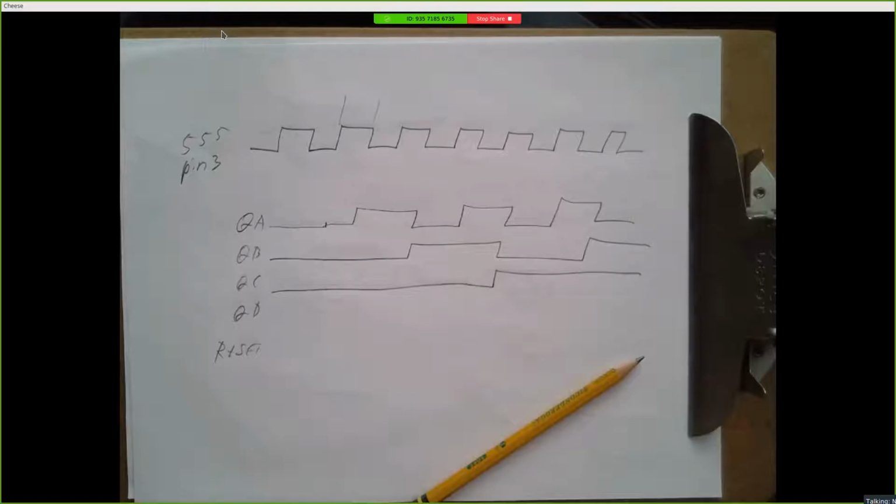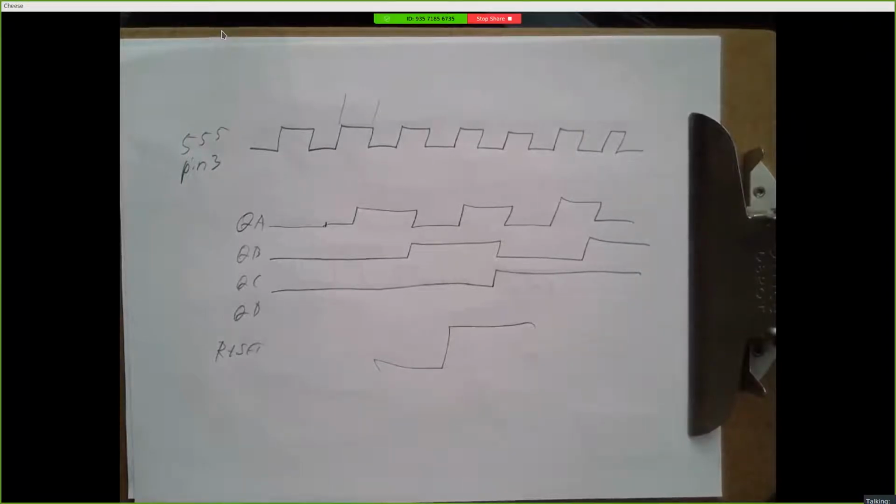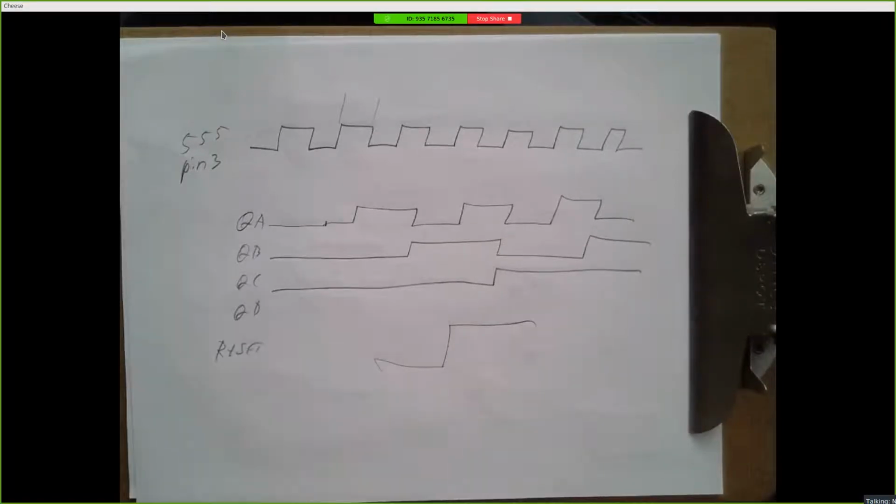For experiment 1 on Lab 5, I saw things like, for Lab 5, I built a clock using a 555. Here's the waveform. And then there was this drawn on the page. If you don't know anything about Lab 5, is that enough information to reproduce what you did? Absolutely not. How did you hook up the 555? There were resistors, capacitors. Where did you put those? Where did you take the output? How did you power it? How much voltage? Where did you apply the voltage? Where did you apply ground? And was this observed, calculated, or predicted? Everything you need to reproduce the work that you did should be in your lab report.